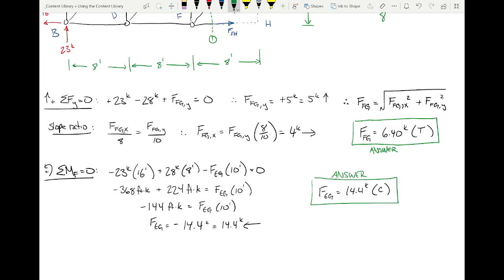That's what matters, okay? So what I don't want to see at the end of a truss analysis, if we're looking at internal axial forces, is that the force in member AB is 20 kips to the right. I don't care if it's to the right or to the left. That doesn't matter. What matters is tension or compression. Because again, the only reason that it's acting, let's say, to the left is because we cut a section to look this way. If I cut a section to look this way, it's going to be to the right. So, does that idea make sense? Okay.